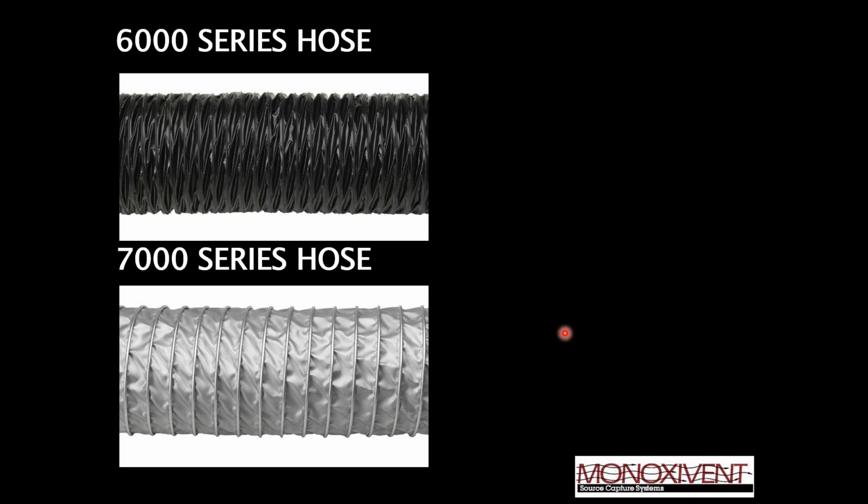So I'm introducing 70 degree air at a 20% clip into the 1700 degree air. It starts to dissipate immediately, and then the velocity or the movement helps to dissipate it. So if I need 30 feet of hose, I may be able to do 10 feet of this really expensive hose, and then the other 20 feet of a lower temp rated, lower costing hose. We call that a combination hose. We can handle the application, but still be cost effective.